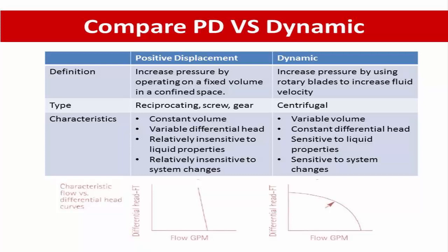Look at the performance curve of positive displacement and dynamic. For positive displacement, you can see the differential head is relatively independent of the flow rate, different from the differential head of the dynamic pump. The head of the dynamic pump changes relatively with the flow rate.